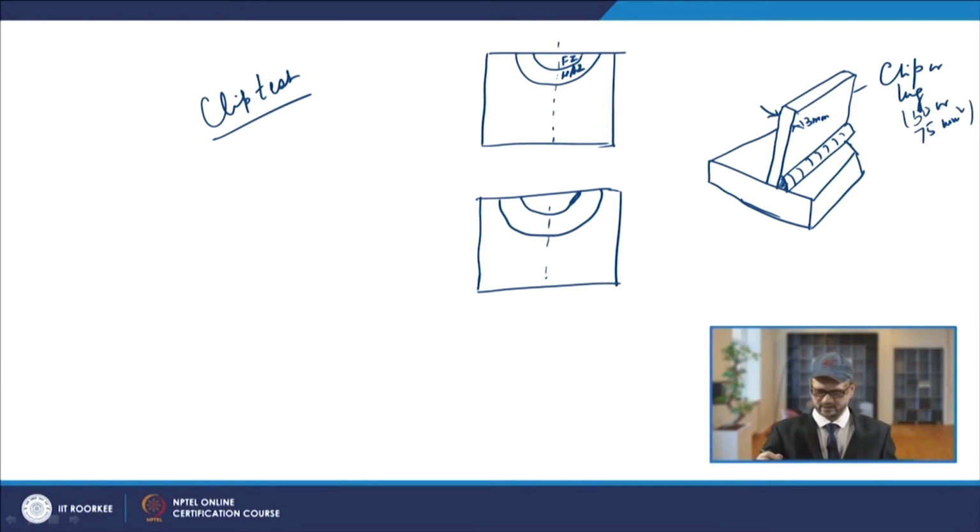That area will be attached to a steel plate. This steel plate is made of alloy steel, and the clip is made of low carbon steel, welded with a convex fillet weld. You weld this low carbon steel clip of the requisite dimension onto the plate under normal conditions, then allow the weld to cool to room temperature, and then you try to break it by hammering. So, suppose you have this specimen.